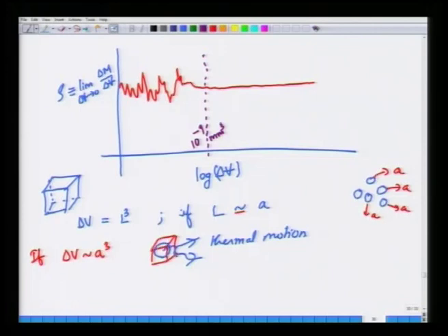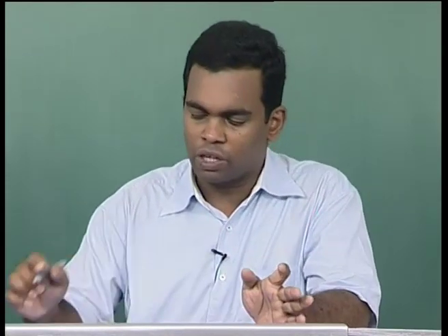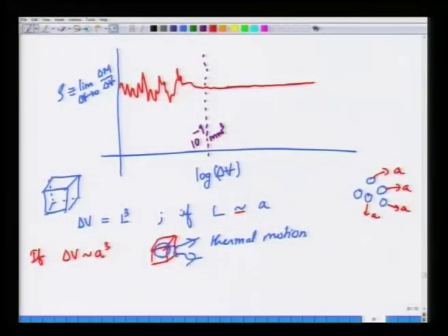That is, when the size of the cube is of the order of 1 micron, the density would have nicely settled down to a flat, constant value. From this point on, regardless of how you choose the volume, the value of the density will remain the same. So, this is the continuum value of density.